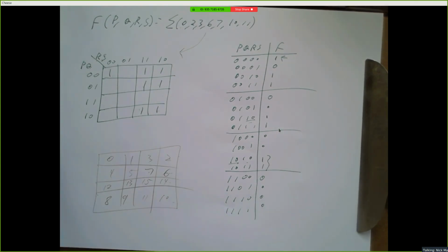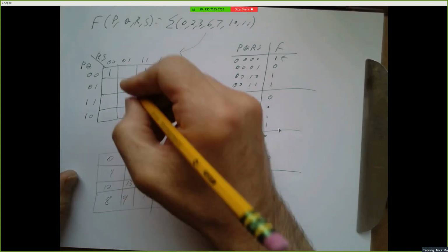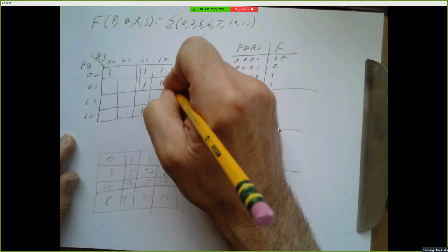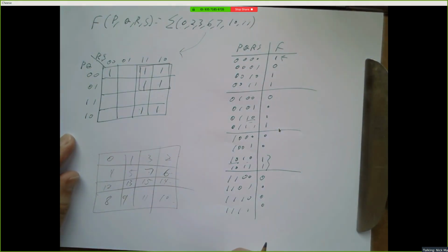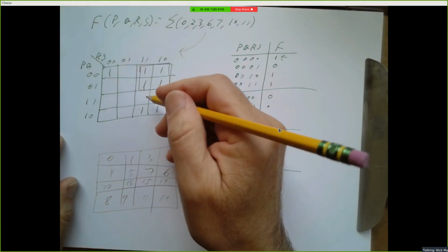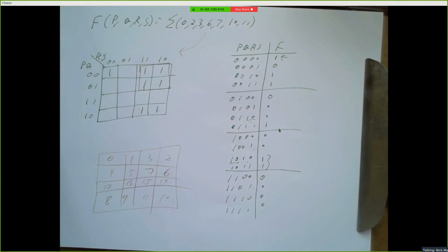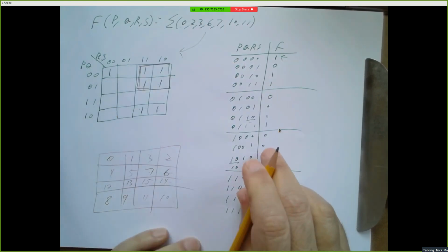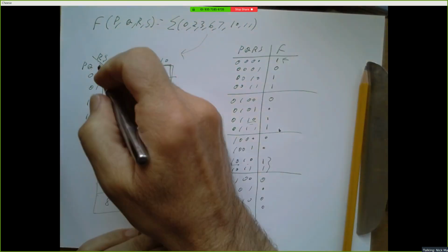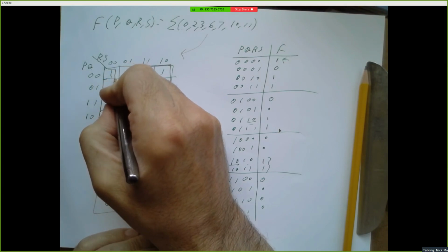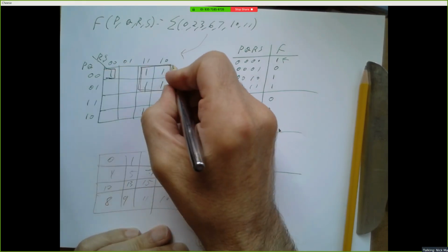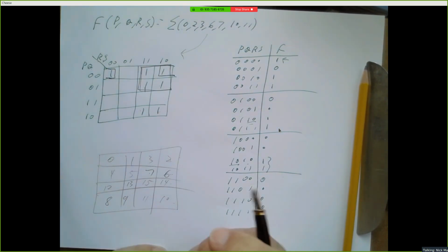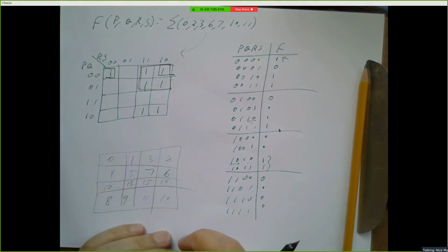Alright, so covering with rectangles, this was the part that most people lost a few points on. So this is pretty obviously a 2x2 rectangle, okay? We could do it as a pair of 2x1s or 1x2s or 4 1x1s, but bigger rectangles, fewer rectangles, that's what we're after. So putting a big rectangle around here, that's definitely a way to go. Okay, this one over here is all by itself, but we can wrap, right? So that rectangle can wrap over to this rectangle, and we've got a 1x2, which is better than a 1x1.